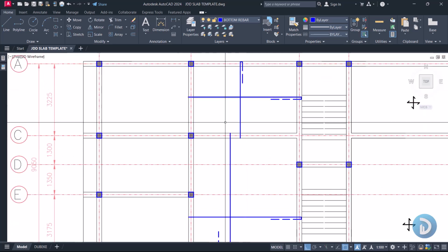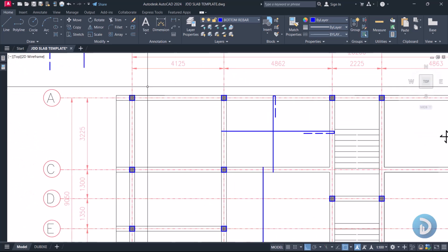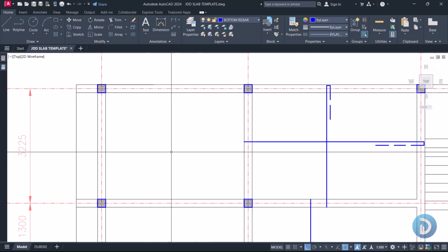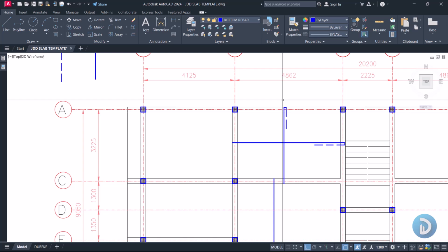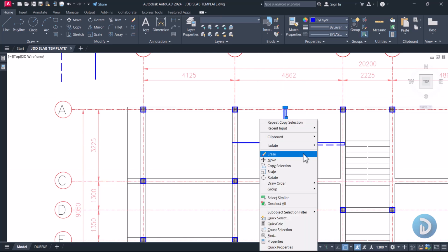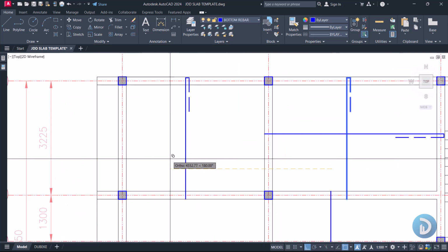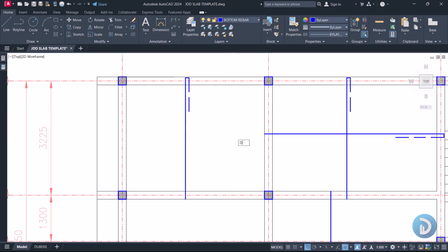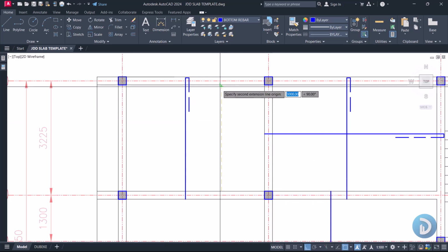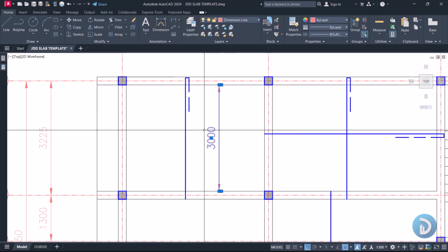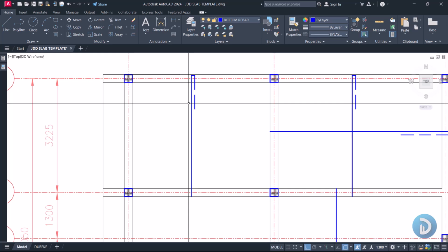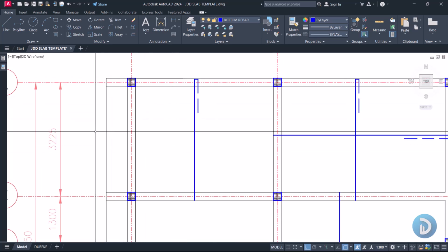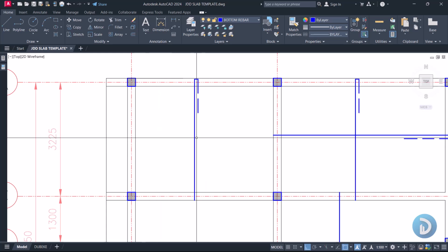Okay, so now we are done with this other section, and let's move on to the left hand side. So same thing we did for here. This reinforcement is also what we will use for this other part. Okay, because they also have the same width, and they should also have the same return length of the top bar. All right, now let's deal with the horizontal axis of this very panel.